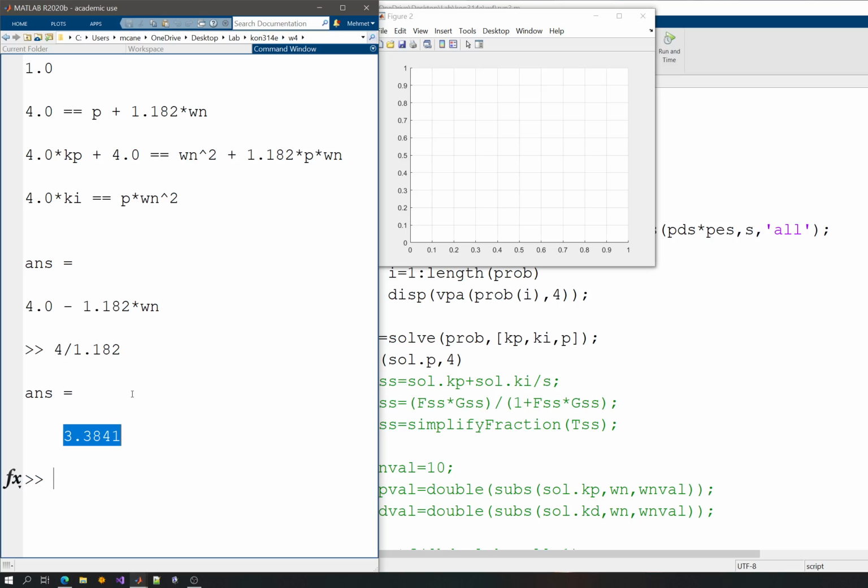Now also keep in mind that I want to maybe maximize this parametric function, since I want to have a dominant pole pair, and this pole that I'm examining now, the value of P, should be as big as possible, since it will be further away in the s domain. So it makes sense that I want to maximize this. So if I have, let's say, omega n 0, it should be 4. If I have 1, I guess this is equal to omega n 1.